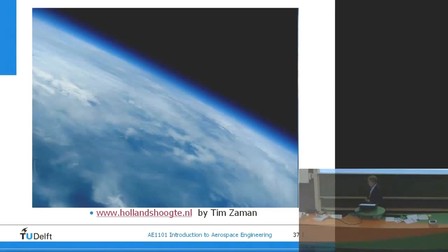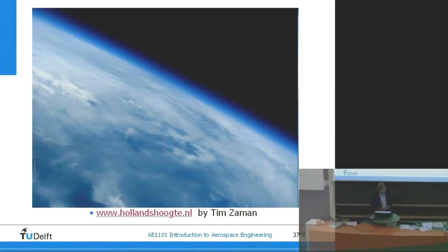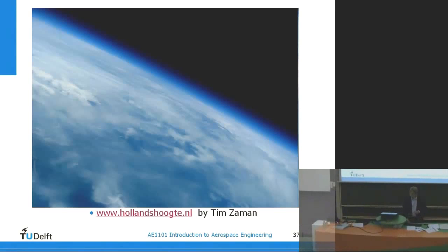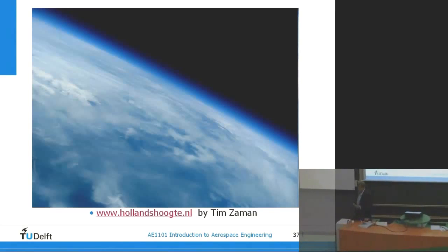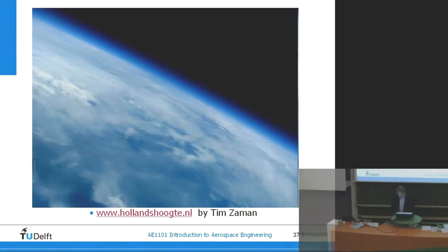So, this altitude, the pressure difference. Let's study the atmosphere a bit more. If you see what we have done, we've basically looked at a law which is known as the hydrostatic law. Of course, we prefer to call it the aerostatic law, but it's the same. And that has to do with the change of pressure due to altitude. And this is the main driving force of the pressure difference in the atmosphere.